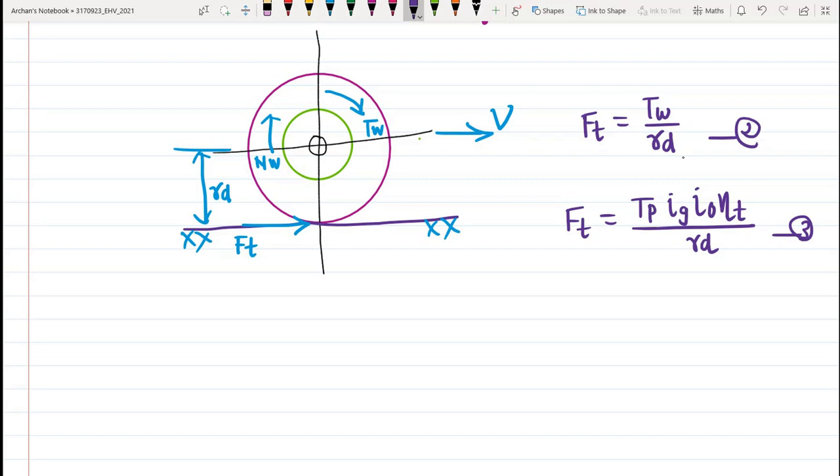The friction in the gear teeth and the friction in the bearings create some losses in mechanical gear transmission, right? So the mechanical efficiency will somewhat reduce. For example, for the clutch, the mechanical efficiency is 99%. For the gears, it ranges from 95 to 97%. For bearings and joints, the efficiency would be 98 to 99%, right?